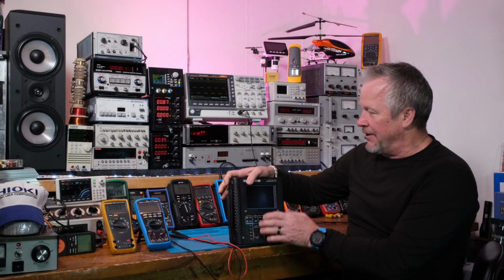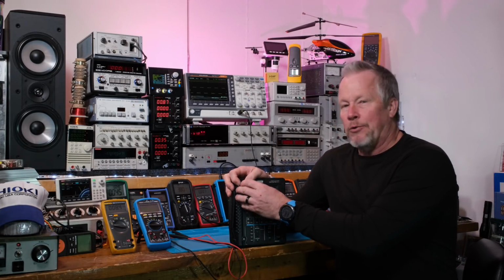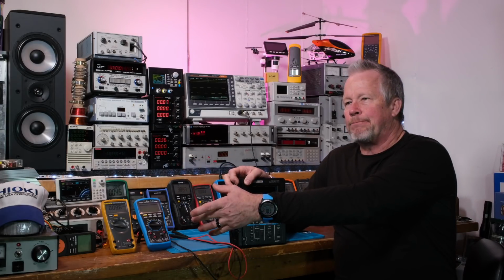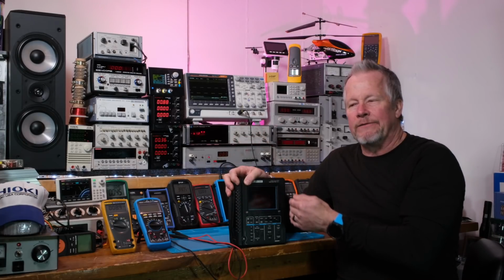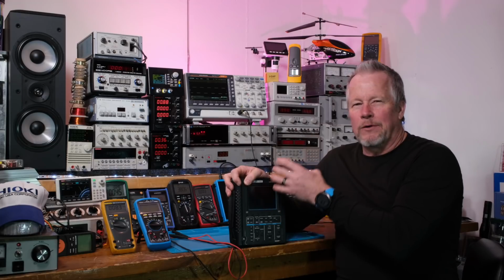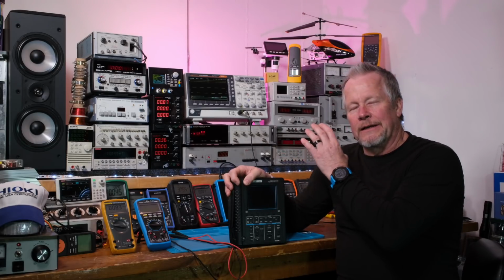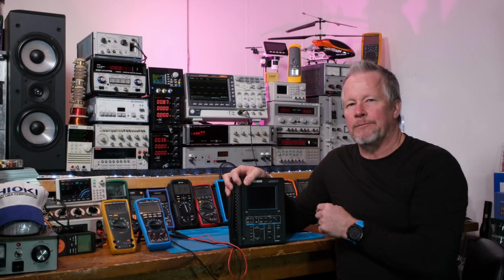When you isolate your grounds, like for a power supply, I'm looking at, say, primary ground, where the primary power comes through, and then I take the power through a transformer, and I put out these secondary voltages, say 5 volts, plus minus 12, 3 volts, that kind of thing. They're all on secondary ground. They're galvanically isolated from the primary side.